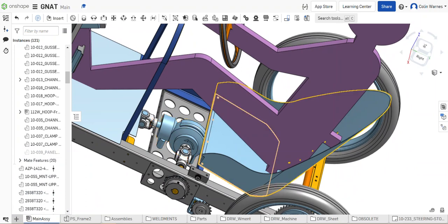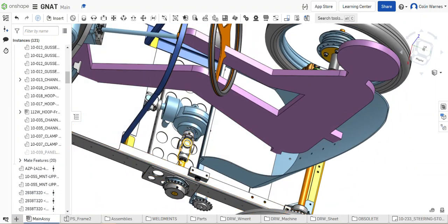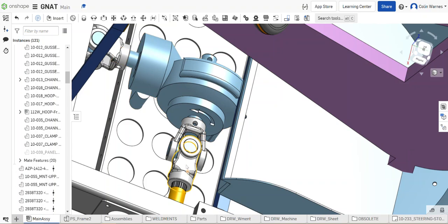So you'll see that I've got the drive shaft, and then another universal joint running over to the sprocket. The big thing is whenever you've got this sort of fixed assembly, you need some sort of coupling to allow for misalignment, because there's nothing to say that my initial design is 100% perfect and the shaft would be 100% aligned.